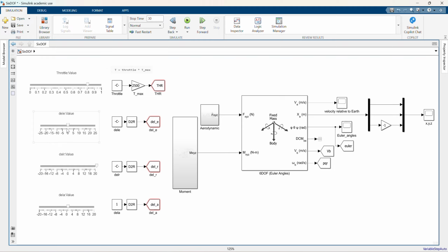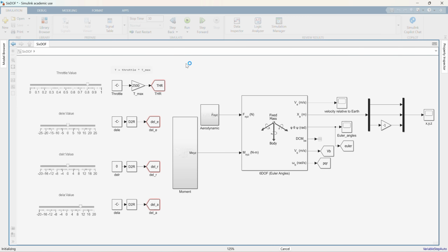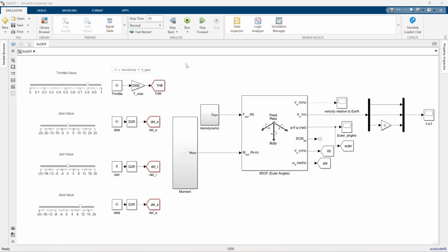Del R, leave it at 0. Aileron, I want that to be about 10 because I want to do an aileron effectiveness test. So I gave the aileron about 10 degrees. Now let's run the Simulink. Let's see if it will work. Perfect. No error messages. Now, when you do this, be prepared. If you see error messages, be prepared to troubleshoot from that, like I was explaining before.